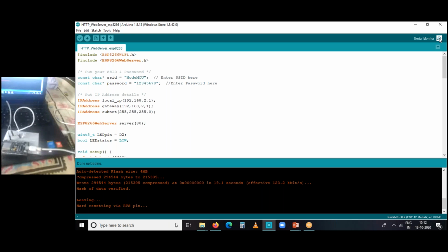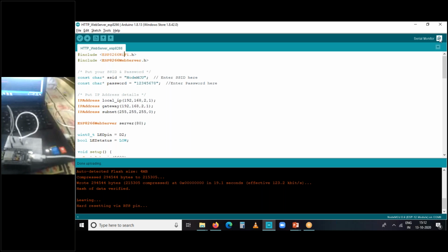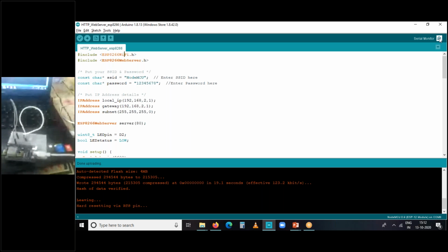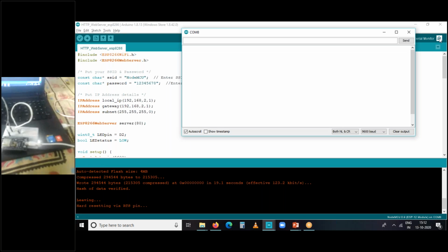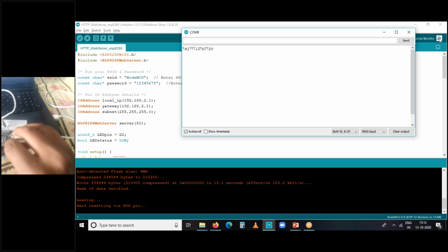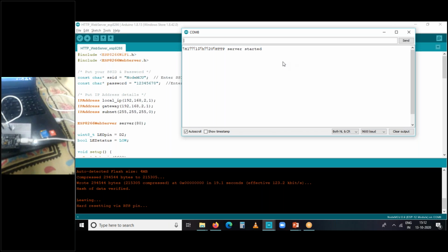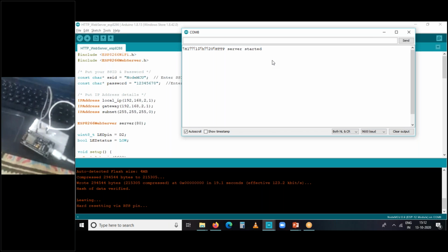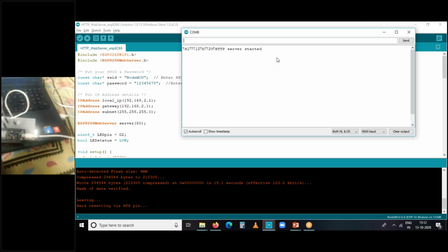There are a lot of versions of NodeMCU. One is Lolin based, one is Atom based, and another one is ESP32, which has inbuilt BLE technology, and another one is ESP01, which has only Wi-Fi, just a pin module that we have to configure ourselves.